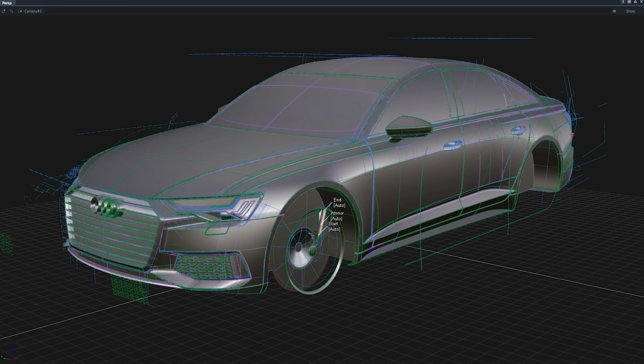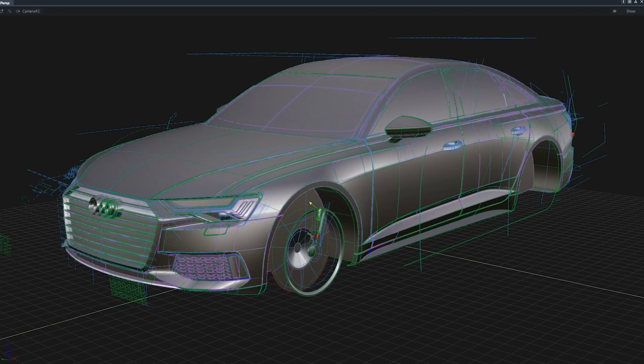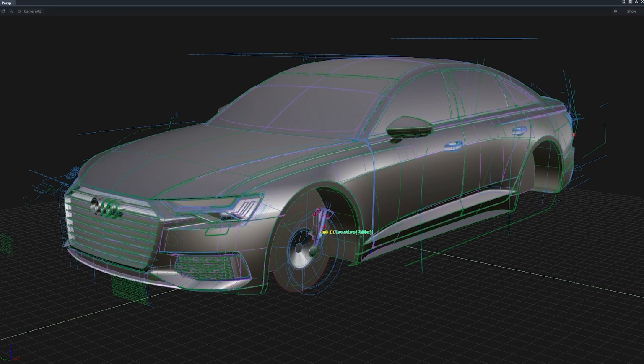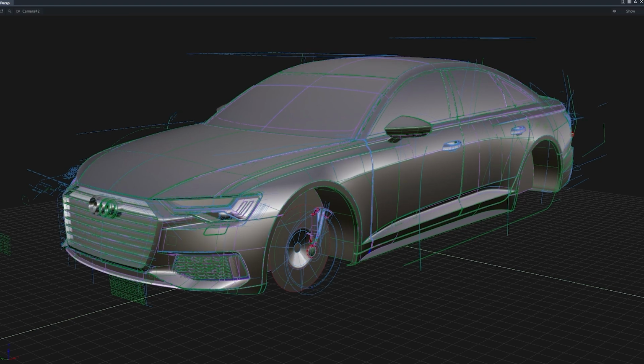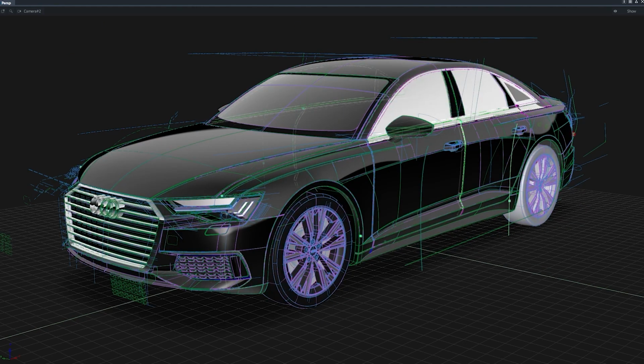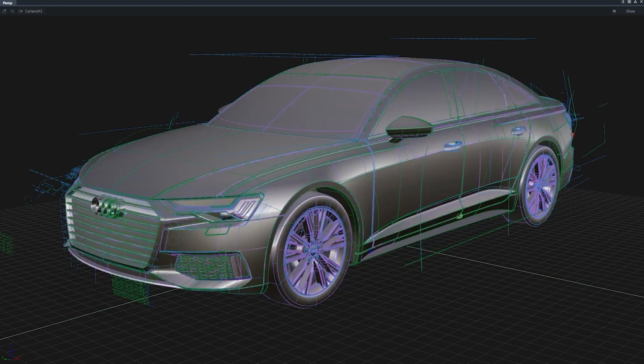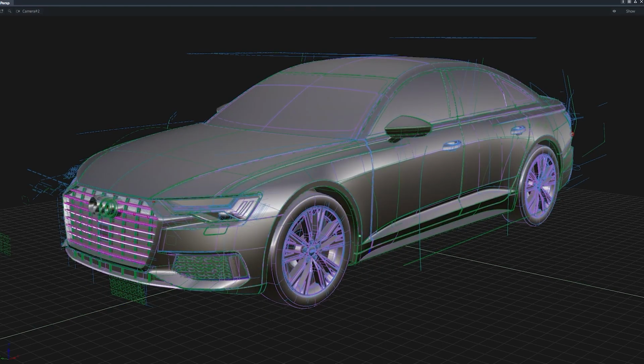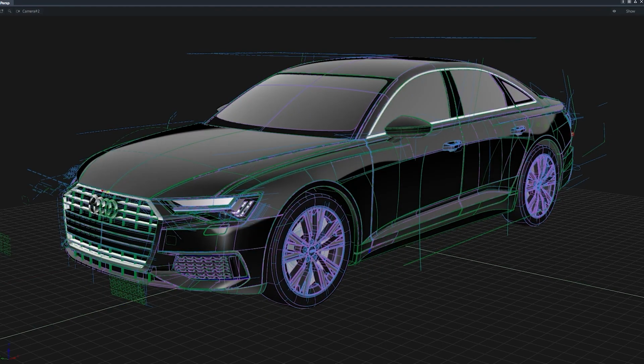You may have noticed during this video a bit of sin in my curvature when I turn on the zebra shader. There's a bit of wobbliness in the zebra shader, and those areas were very difficult for me to tackle, and I believe that was due to my inexperience. I hope to next time generate stronger theoreticals and have a cleaner zebra shader before I add in those fillets and shut lines.